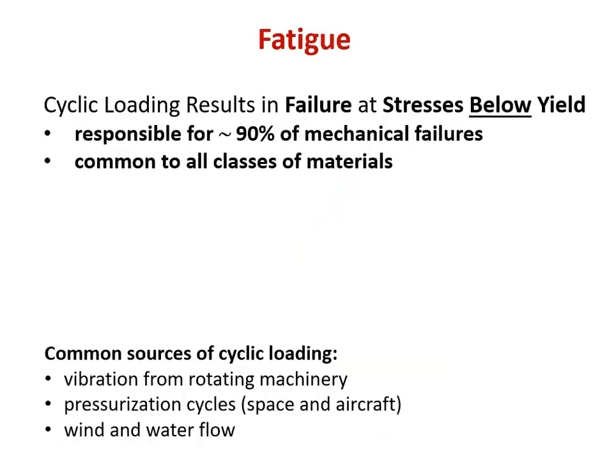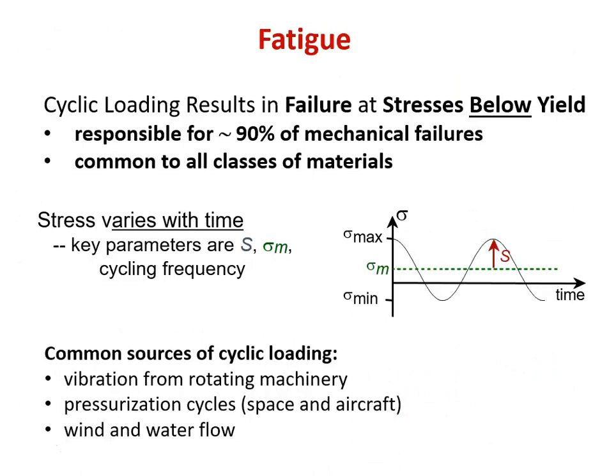So fatigue, this is one of our difficult to predict, or they're predictable but difficult to inspect types of failure. This is something that's somewhat feared simply because it's what we would consider insidious. You can have a material that is subject to cyclic loading, for which we will get failure at stresses well below yield.